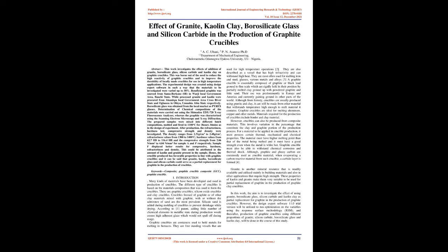Determination of chemical compositions of the materials was carried out using the Shimadzu EDX720 X-ray fluorescence analyzer, whereas the graphite was characterized using the scanning electron microscope and X-ray diffraction. The prepared samples were mixed into different batch compositions, molded, and fired to 1100 °C for 3 hours 34 minutes as in the design of experiment. After production, the refractoriness, hardness test, compressive strength, and density were investigated.